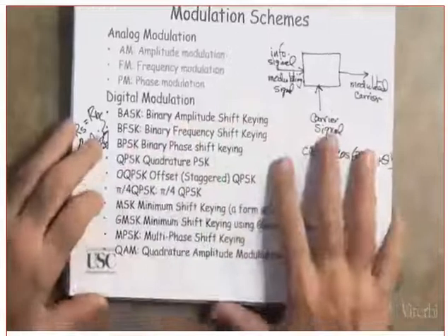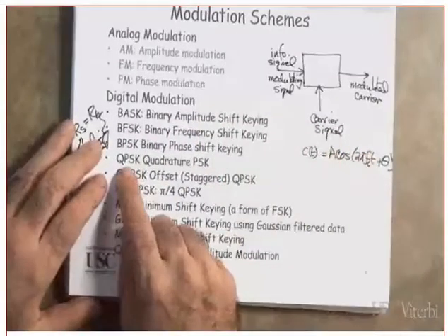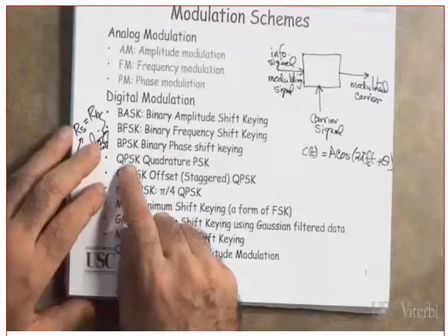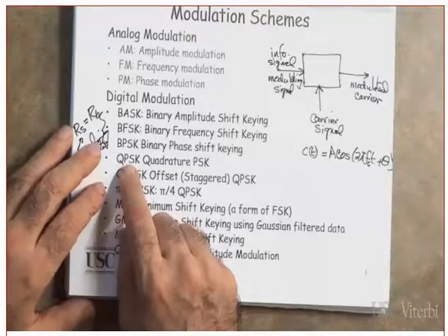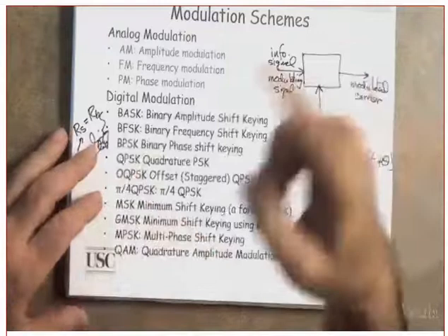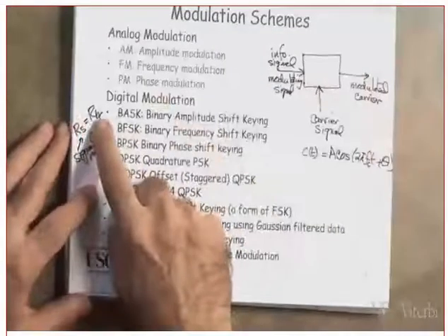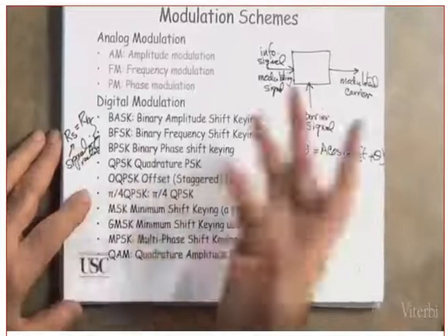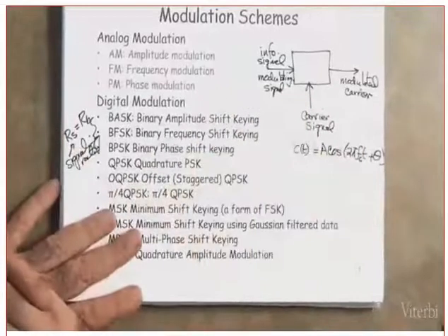Okay, good. Now, then we have, of course, QPSK, which is the quadrature phase shift keying. Clear? Which is widely used, even now. In this case here, how many bits go in? 2 bits go into the modem, 1 symbol goes out. Which means what is the relationship? RB equals 2RS. Or RS equals RB over 2.